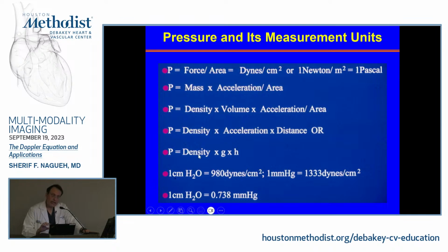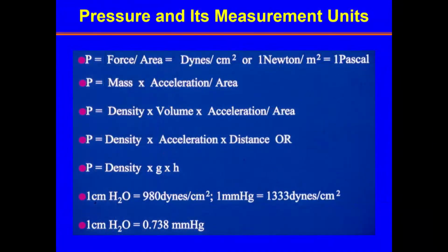If we are looking at a stationary fluid at a certain height above the center of gravity, that acceleration becomes the free fall acceleration. And so usually what you will see expressed when we estimate pressures is in millimeters mercury or centimeters of water. So we need to see how we get to centimeters of water or millimeters of mercury from that expression.